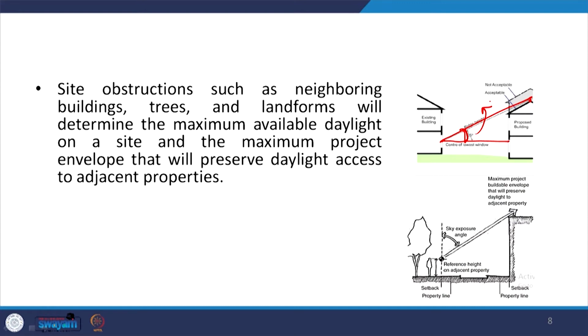Some green building rating systems also talk about the upper limits of this obstruction. In case the obstruction is greater than a certain number, the window is not considered for daylighting calculations or for bringing in outside views. In IGBC, this limit has been set as 70 degrees.